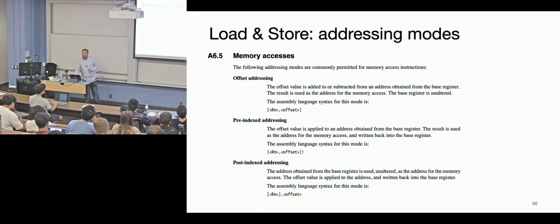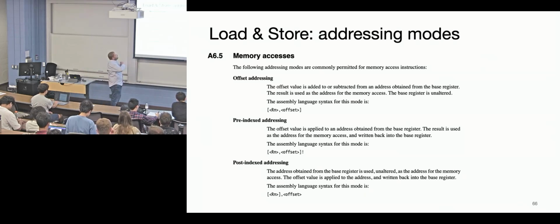All right, so we're getting a little long, but we're getting there. One of the big ideas with loads and stores is how we can do some offset indexing. Oftentimes you have functions that iterate. I want to place things in memory with a particular offset, so they've given us functions for that. You can have normal, place it in a thing. You have offset indexing where you say, place it at this address plus 4 plus some number. And then you have options to do the indexing before or after you've done the load and store. We'll walk through some of those examples to make it more clear.